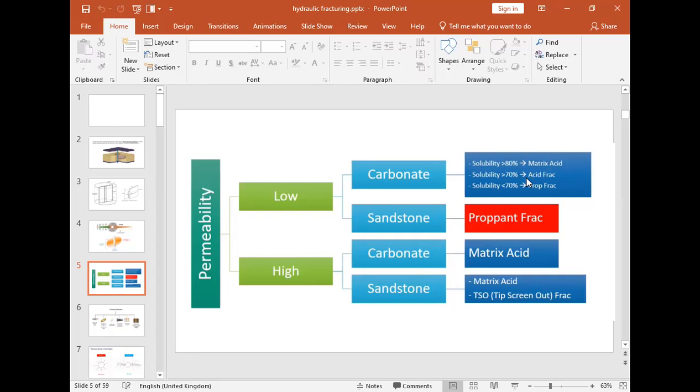It goes in to treat and remove those chemicals that are blocking the pore spaces, so that it washes away all those chemicals, and at the end of the day, that region becomes porous. But acid frac can also be carried out in a situation where it is not only injected to do the treatment, but the aim is also to create some highly conductive pathways. So you're doing two things at the same time. So for a carbonate reservoir, we can do that.